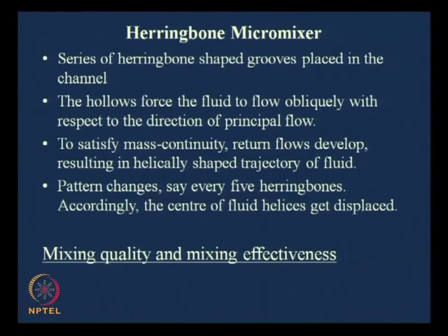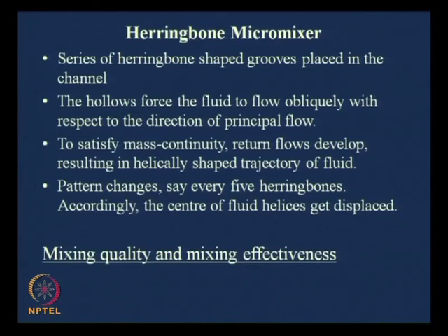So you have a cross flow going on, and then it hits the wall, and then it has to come back. What you have is a helical shape; the cross flow is generated helically. So, to satisfy mass continuity, return flows develop, resulting in a helically shaped trajectory of fluid, and the pattern changes every 5 herringbones, say.